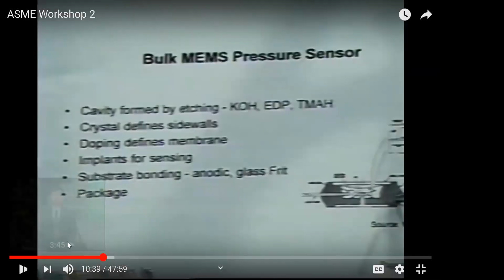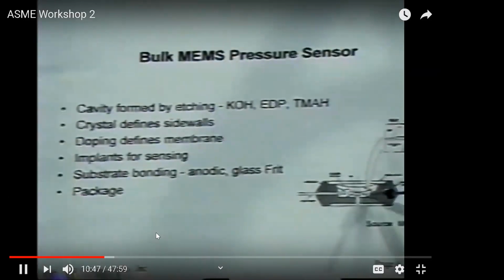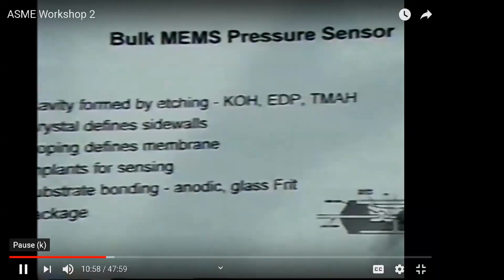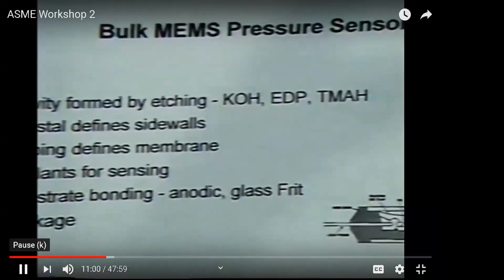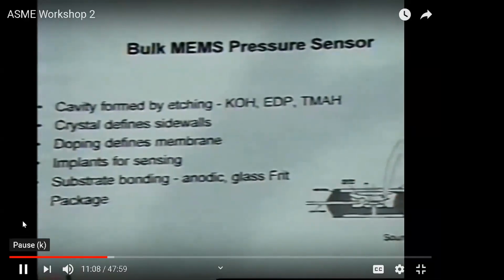Machine pressure sensors, as we do not have one. And you may not be able to see this on your screen right now, but in your notes you should be able to see that inside of a package, there is a pressure sensor mounted on a substrate, and the deflection of the membrane, which is on the top, determines the strain that is finally read off, and that strain determines what the output voltage, or the output voltage difference, will be of the bridge.